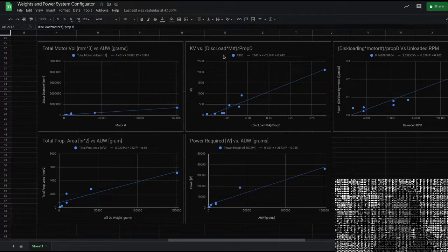So this is kind of a rough area because when you get such a large domain, the actual KVs at the top end up getting really low. So this is an area where I think it'd be better if there were a spreadsheet only including drones 2 inches and below width, or drones 55 pounds and up. Because if your data is based on a whole bunch of human carrying drones, or a whole bunch of tiny camera drones, and you try to calculate the KV needed for a big drone, you might get a negative number and it can create errors in your spreadsheet down the line. So that's the usefulness, I think, of breaking it down into sections like that.